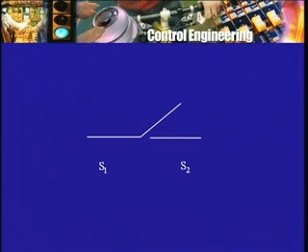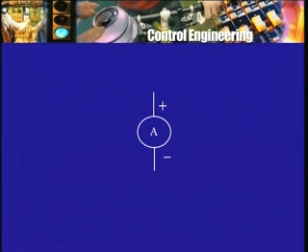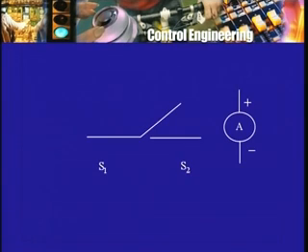If you do this, you do find that after you have opened S1 and closed S2, the activity does not stop immediately, and if one connects an ammeter in the circuit to see whether there is any activity going on, or connects it to an oscilloscope, one will find that indeed activity goes on in the circuit even after the source has been removed. Current continues to flow for quite some time, and under certain conditions the current may in fact be oscillatory. That is, it will go through positive and negative values and keep on oscillating for some time before the current becomes almost 0.